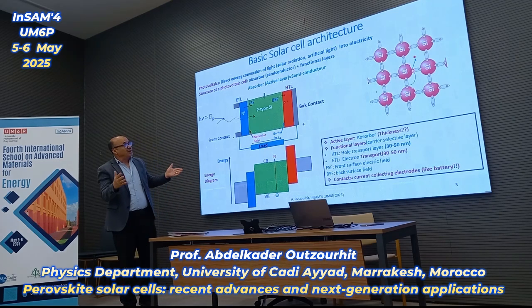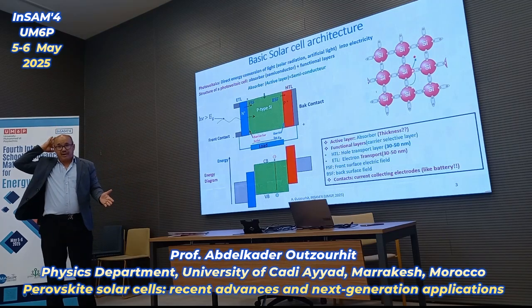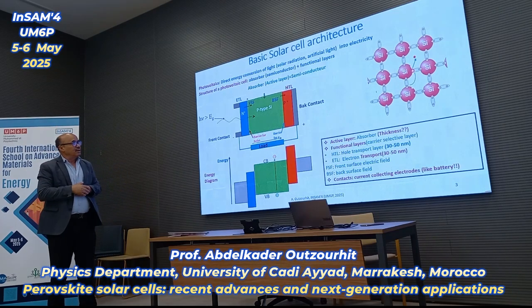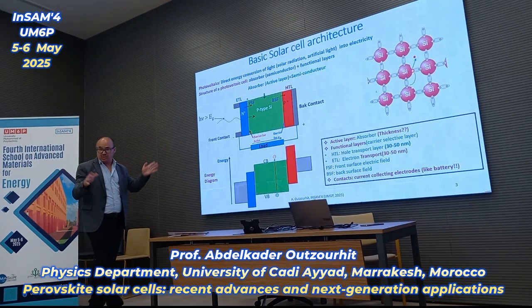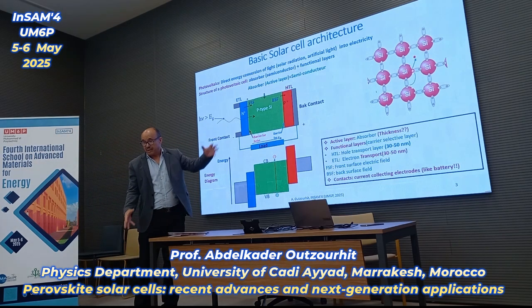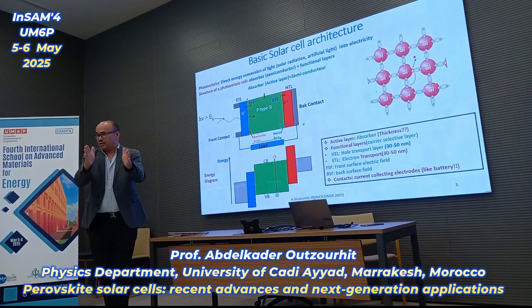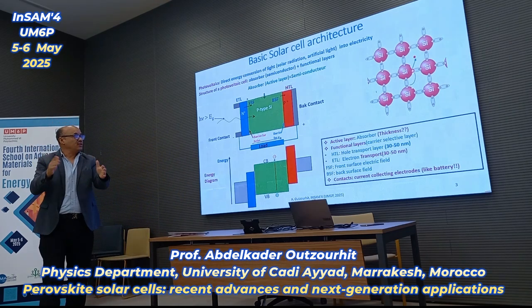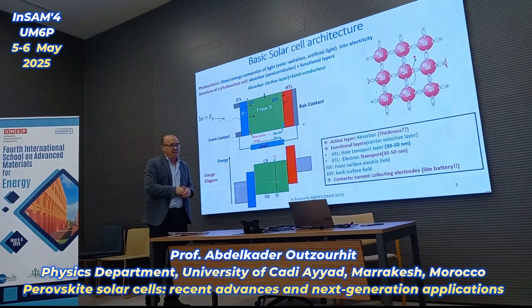You cannot use insulators, because they need higher energies to liberate the pairs, and they are poor conductors. Metals, everything is already free, so you can't do it. So the only choice is a semiconductor, because you can liberate electrons with photon energies in the solar spectrum. That's why I use semiconductors, mainly silicon, as we'll see.